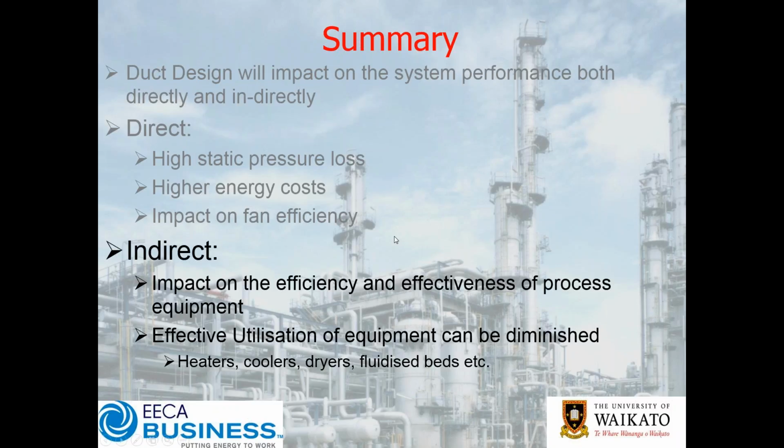And so in summary, it's very, very important that you pay close attention to where your ducts are and what they look like. And the key things to look for is really measuring your static pressure to understand where you're losing static pressure, and then obviously looking at your duct transition sections and any change in direction. As a general rule of thumb, if you're losing more than a couple of hundred pascals across your duct work, you've got a problem and you need to look at it.